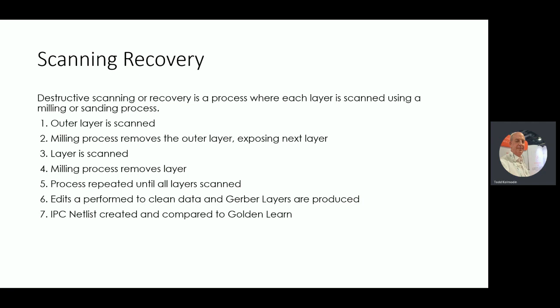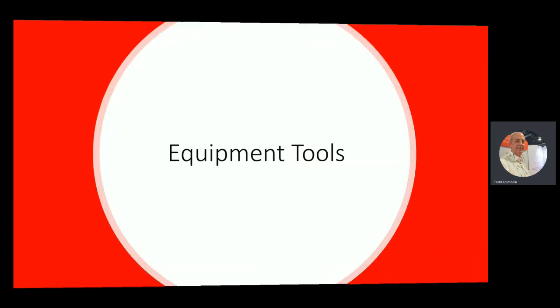And so when you compare the two, you can find out if your netlist is golden, or what you create is golden, or it could identify some differences where you can actually go through and look at the layers to see where the actual discrepancy is, because you've created all the Gerber photo tools, and now you can look at both of the options.